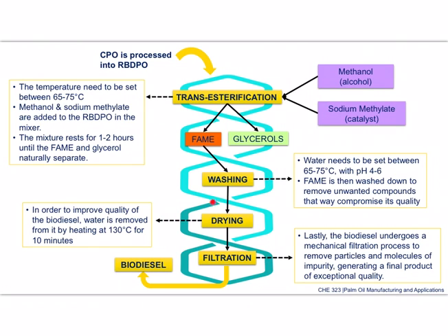At this position, you can get rid of the water or the moisture content that you get from the product of washing. Once you dry the fatty acid methyl ester, there is no more water that you can observe in the product that you have. So the final product that you're going to get is called biodiesel.